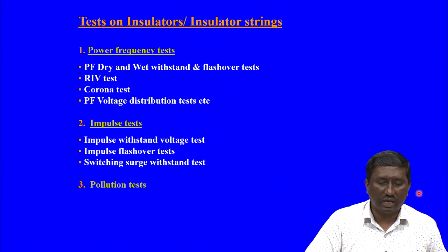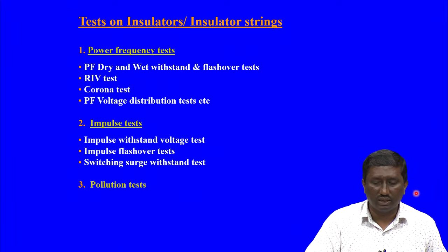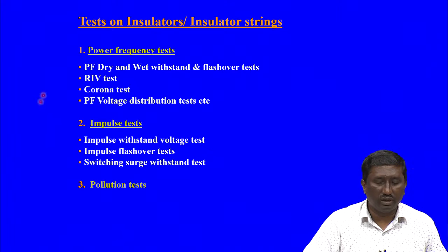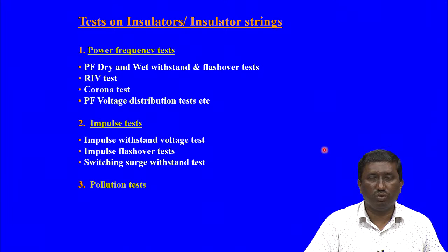So, various type tests as per the international standards are being specified for different equipments which are used in high voltage and extra and ultra high voltage range. Some of the tests include the power frequency test, where these are operated at 50 hertz. The power frequency dry is for clean conditions, and wet is because of the rain which the equipment could see in the service. So, this dry and wet conditions have to be simulated in the laboratory, and the power